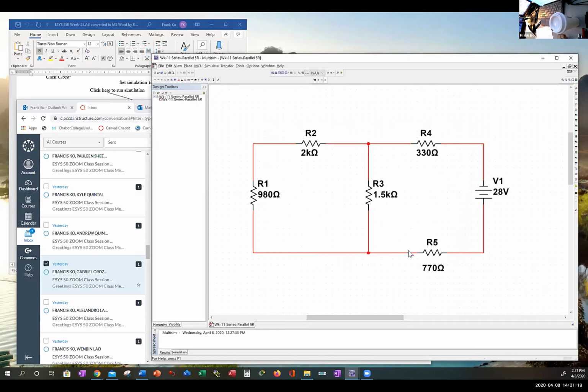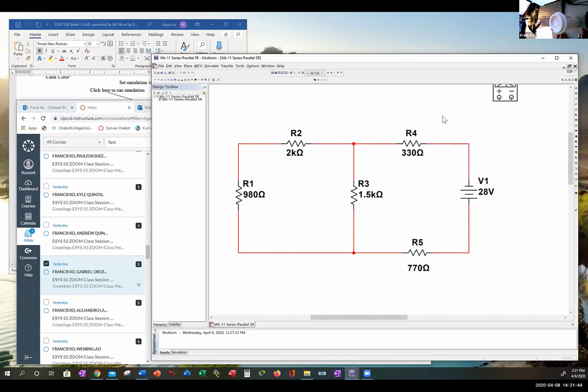That being said, now I'll show you how to make measurements of different things. If I wanted to bring in a meter, I have a variety of different meters: logic, word generator, frequency counter, Bode plot, 4-channel oscope, watt meter, function generator, multimeter, yay. So the multimeter will come here, and I can then place it to make a connection across any component. So we calculated R2 to be 8.94 volts.